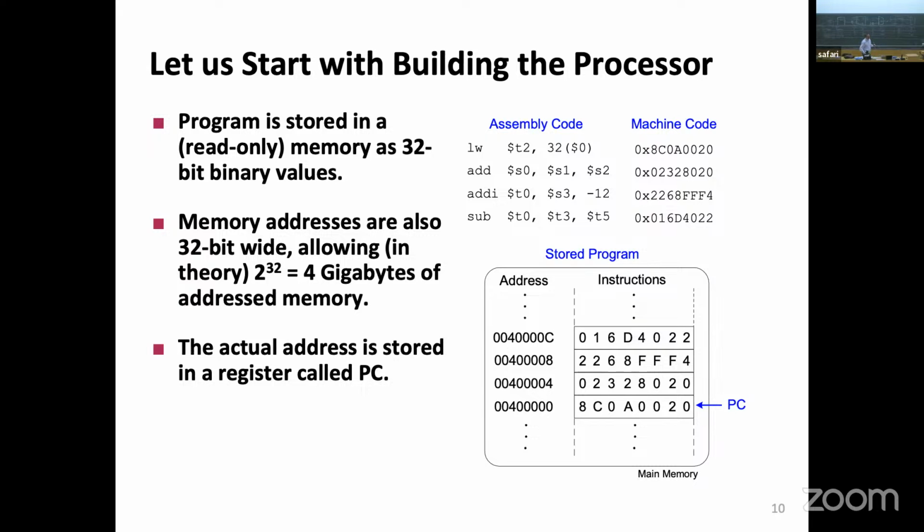Now, branch if equal to is a funny instruction, right? The BEQ has two registers, S0, T1, and then an immediate, a label, let's say, label something. We knew that this label will get translated to an address, which will end up being an immediate. What will it mean? Normally we are at the program counter, so this is where the branch equal to instruction will be. The next instruction will be the program counter plus 4, and this immediate will be an offset to it. We will say jump 10 addresses ahead, jump 5 instructions behind.